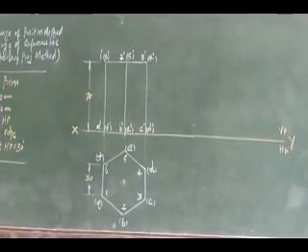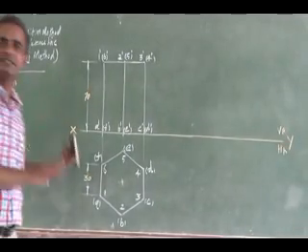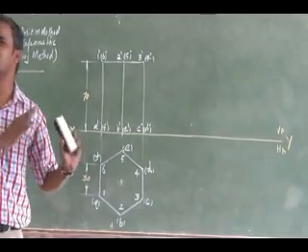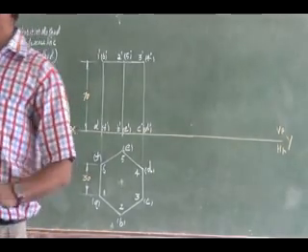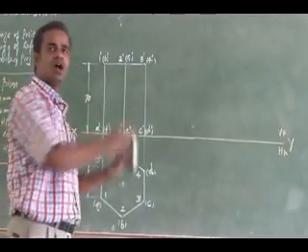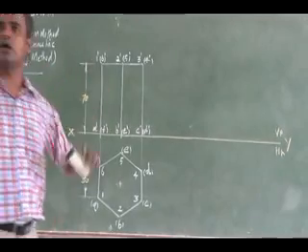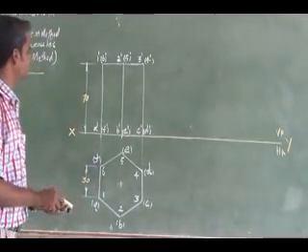Right. So this is the simple question you have drawn. This should be drawn in 2H pencil. It is a light one. This is not the final front view and final top view. Now, in the second step, you are going to draw the final front view and final top view. That you have to darken it. You see here in the second step.